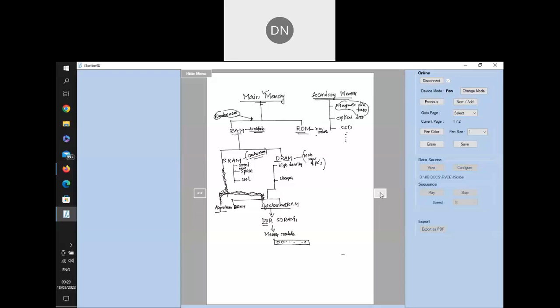So these are the types of RAMs available, SRAM and DRAM. Now we'll see what types of ROMs are available. If you purchase a ROM chip from the factory, it is used for storing the program one time. That means at the time of manufacturing itself, the manufacturer writes the program and gives the ROM chip. We call it read-only memory, ROM itself.